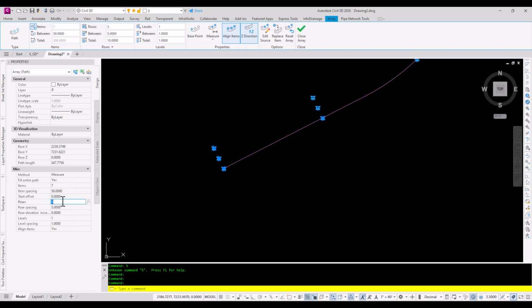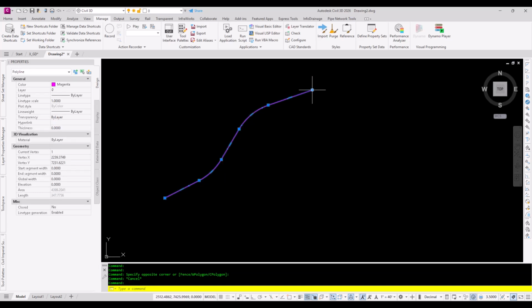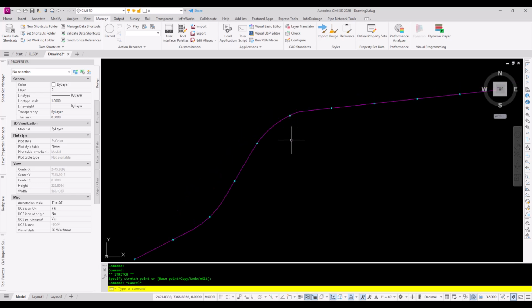I like to run that path and then change our settings how we would like it. Now, what if we need to modify the polyline? What if the road changes or something updates and we just need to move this line way over here? And you see it added our fire hydrants along, but now we have this kind of bump. It doesn't work right. If I fill it the same 100-foot radius we had before, see it filled it in and made it right.